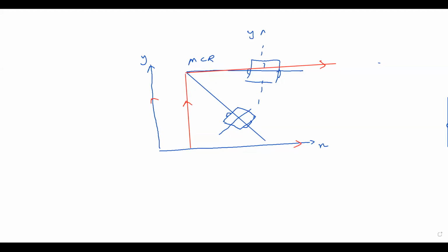Say the robot is turning like this. The momentary center of rotation (MCR) is here. If you draw two lines from the MCR to the center of the robot, so basically we are taking a point of the robot, X1, Y1 is a momentary point of the robot. If you draw two lines, X1, Y1 and X2, Y2, to these points, the angle is beta. And this is the line corresponding to the X direction, and this is for the Y direction.